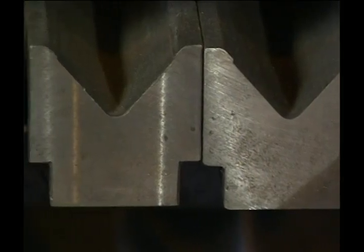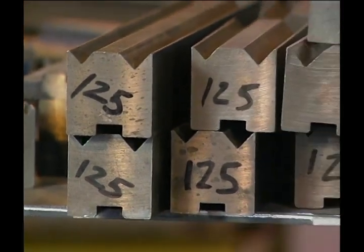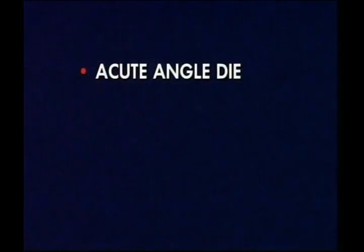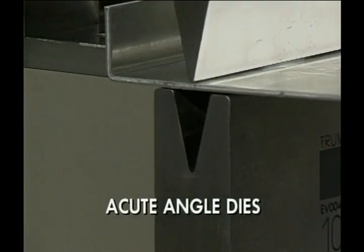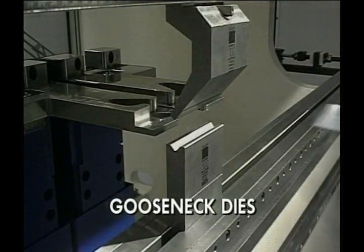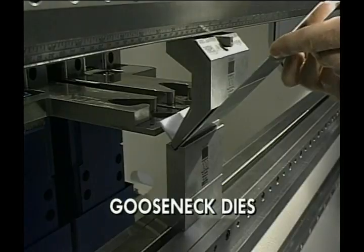Dies are the tooling that determine the shape produced on press brakes. The most common type of bending die is the 90-degree V-shaped die, but many other types are used to produce shapes, such as the acute angle die, the gooseneck die, the offset die, and the rotary bending die. Acute angle dies are usually used in air bending, where accuracy is not critical. Gooseneck dies essentially are V-bend dies, with clearance for return flanges.